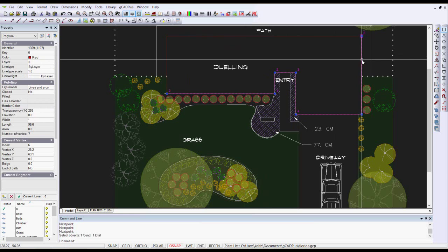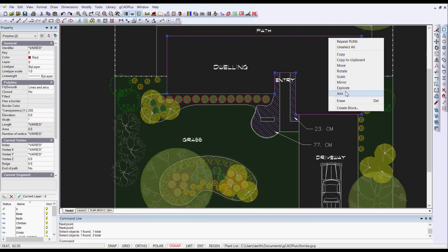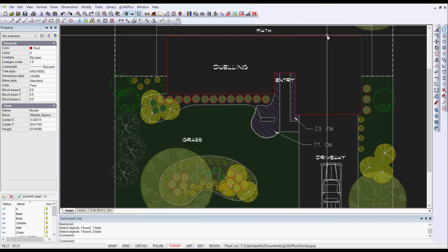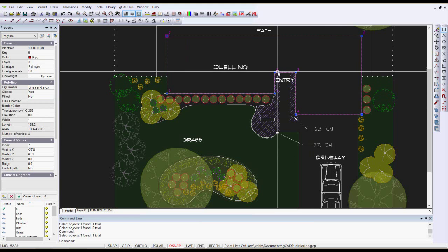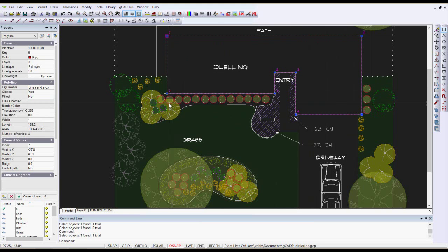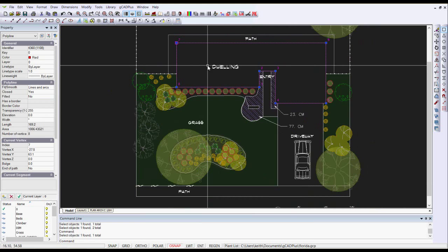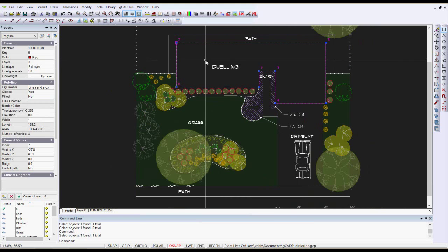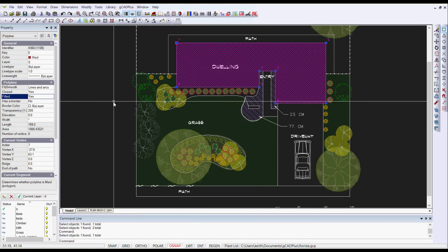Now we've got two polylines, that one and that one, so let's join them together and then select the polyline. So point 1 is there, 2, 3, 4, 5, 6, 7, and back to 0. So 0, 1, 2, 3. So that looks to me as though that might offset properly. It hasn't got that muddled series of point picks. So let's fill it. So we'll say filled, yes.